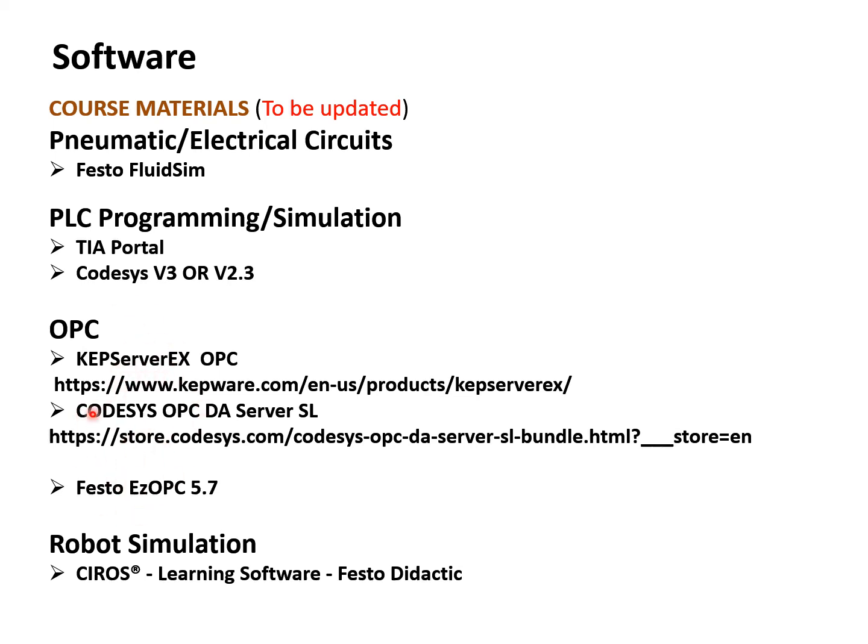Okay, all of these OPCs have some advantages and disadvantages. The issue is that all of them need at least these two. They need a license, but with this one you have 2 hours to work on the OPC, and then after 2 hours you have to restart it. So that's why this is the best one, I guess, and it's designed for industrial systems. In huge factories and industrial setups, they use this KEP server.